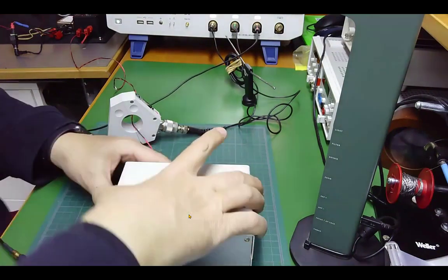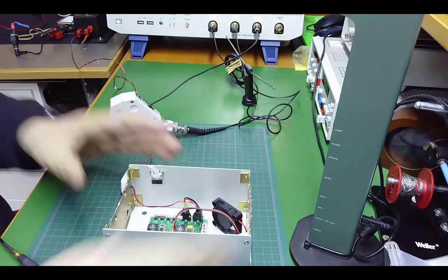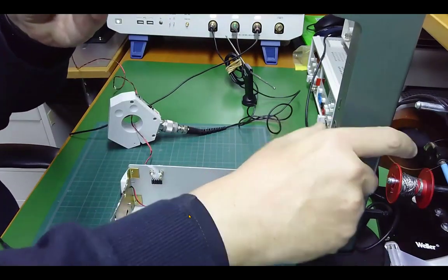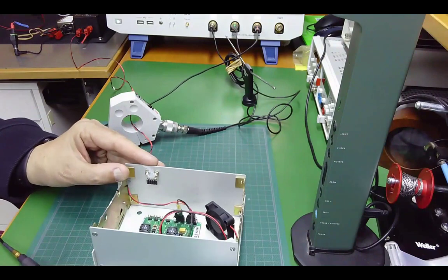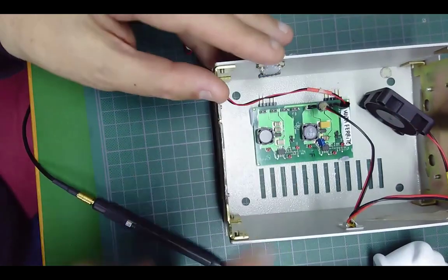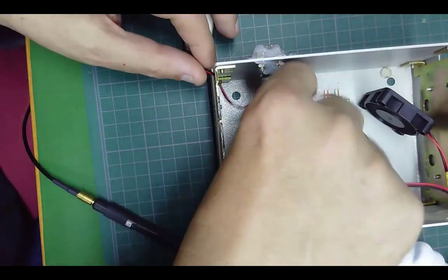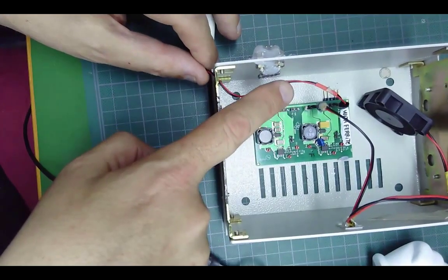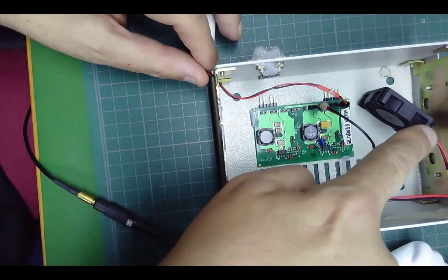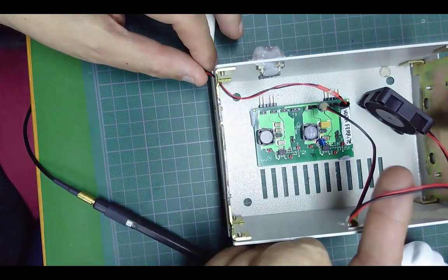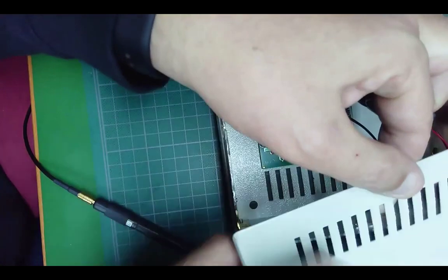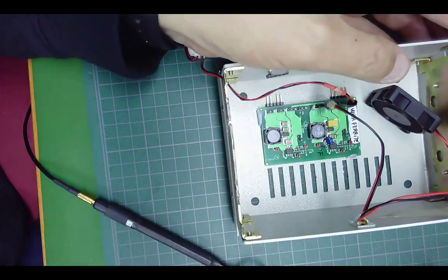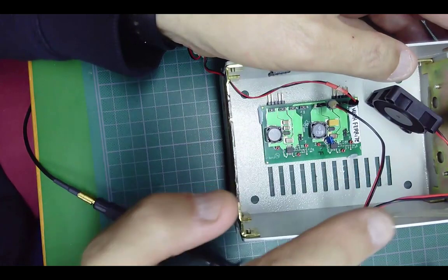Usually, what we try is to solve the problem at the circuit level, no? It's exactly the same circuit I was working with in my first webinar. So let me show you the PCB. I have a PCB that is powered with this cable, this 20 volts, more or less, and the output 12 volts is powering this fan. And this cable, the load cable of the DC-DC converter, is the cable that is going close to the slots in the cover of the enclosure, okay? And the energy that is here is being coupled to the slots, no?